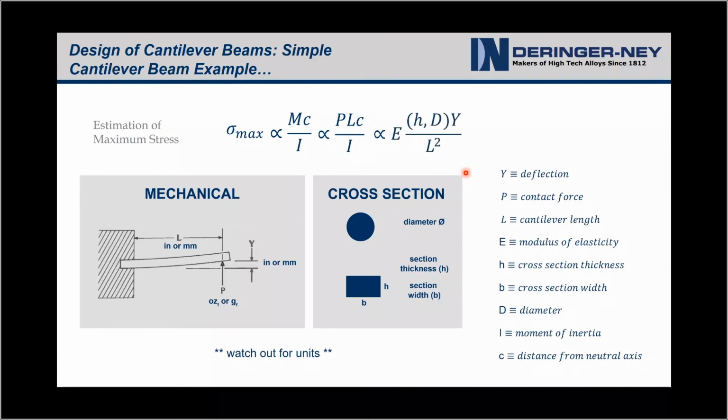But really, if we want to understand this, it almost counterintuitively looks like, to minimize the stress, you want to increase the thickness and the width of the beam, which is kind of hidden, because these are also in the load, since we're looking at a fixed deflection system.